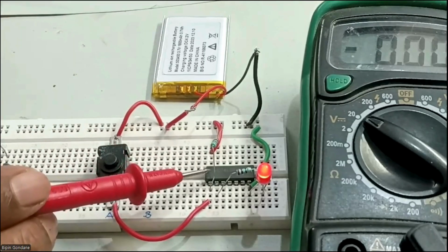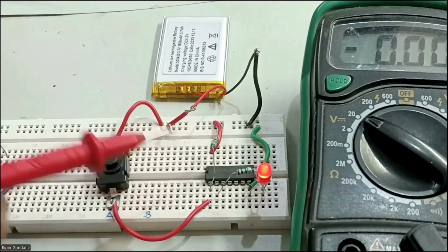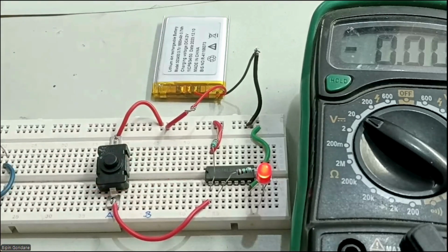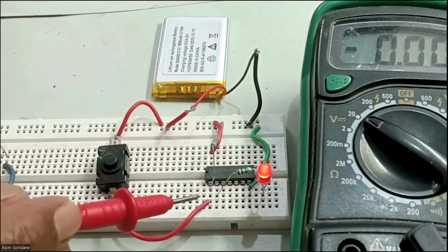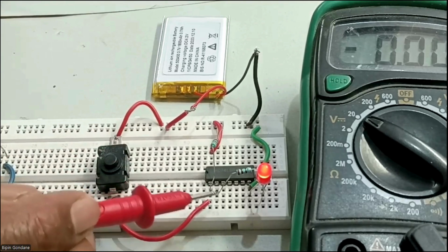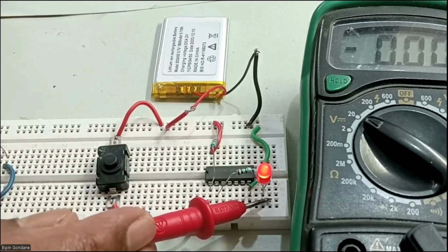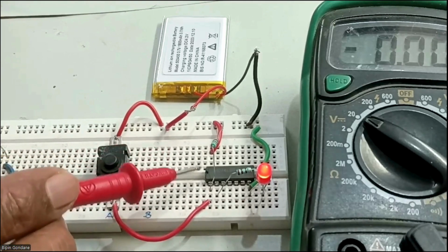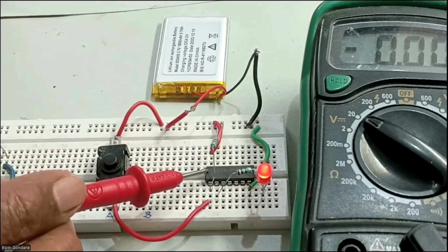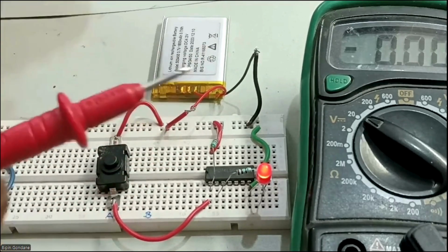Another IC is the 74LS04, that is our NOT IC. Please remember, in a NOT gate you have a single input and a single output because it is an inverter. Here I have given one switch connection to pin number 1, and I have taken the output from pin number 2. The other end of the LED is connected to ground, same as before. In all 74 series ICs, pin number 14 is supply and pin number 7 is ground, so I've given the battery connection accordingly.